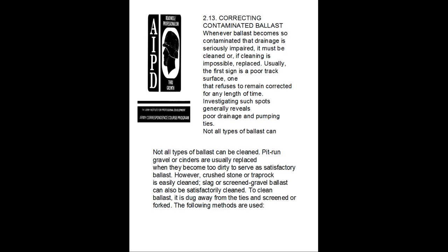Investigating such spots generally reveals damage from pumping ties. Not all types of ballast can be cleaned. Pit run gravel and cinders are usually replaced when they become too dirty or too severely contaminated to serve as satisfactory ballast. However, crushed stone and slag rock are easily cleaned.